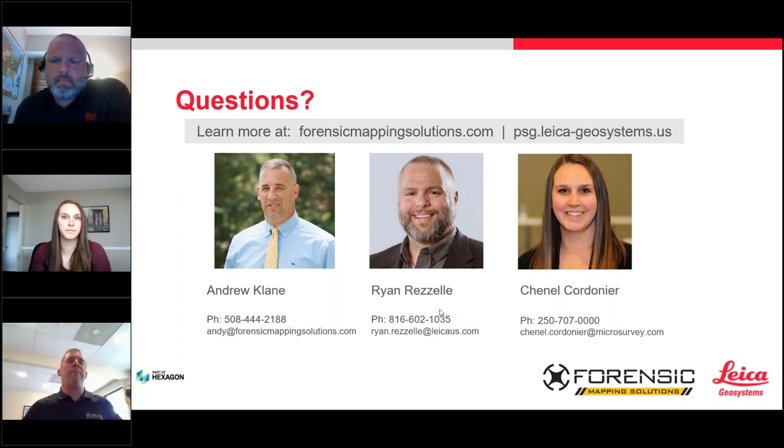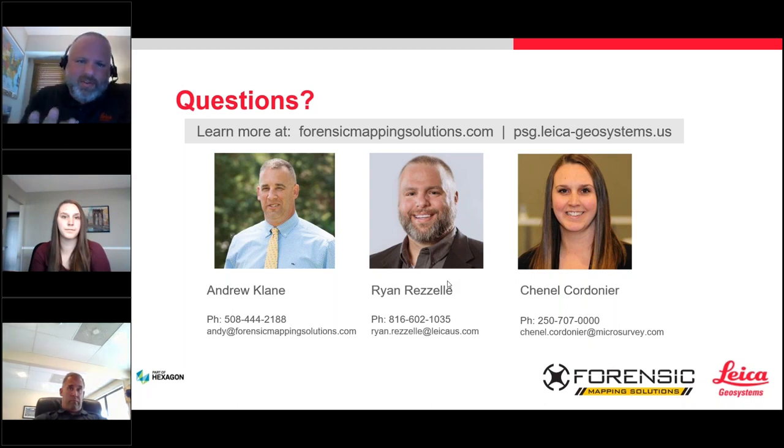Now, Ryan, if maybe you could grab this one as far as the laser scanner. What can we do? Well, it's a great question, and really a lot of it does lie within the Map 360. If you push what you have into Map, Map 360 allows you to create just a wide range of deliverables, whether it be perspective views of different aspects of your scene, evidence reports in which snapshots are integrated with mapping data, PDFs that have point cloud overlaid with drawing. You can have your ortho image overlaid with your drawing. And let me tell you, that's gotten to be such a popular way of sharing, where the ortho rectified image comes in, you create your map over top of it, and you actually publish as your deliverable the combination of the both of them.